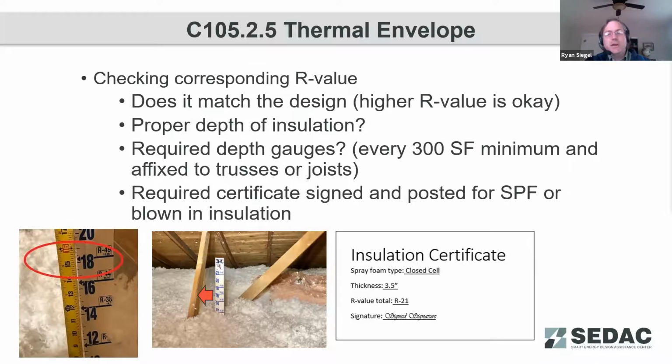So if you do use a blown-in or sprayed-on product, then you do have to have a certificate signed and posted. This may be posted at the entry to the location, such as an attic as depicted here, or that may be found in the location of the mechanical room by an electrical panel or some other suitable location. So that way people know what type of insulation is there, how thick was it, and what was the total R value.